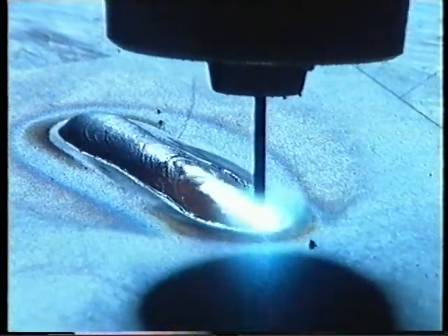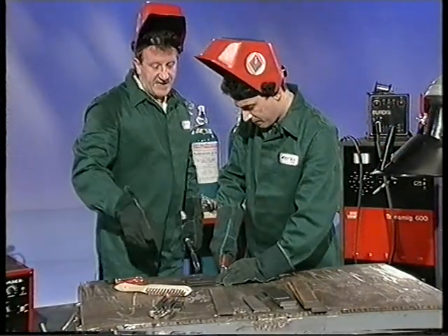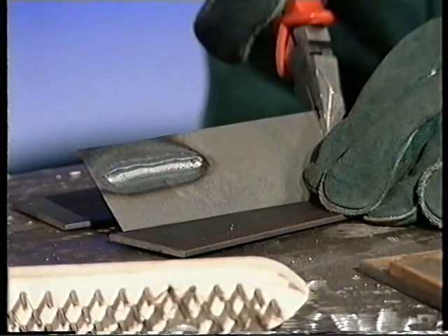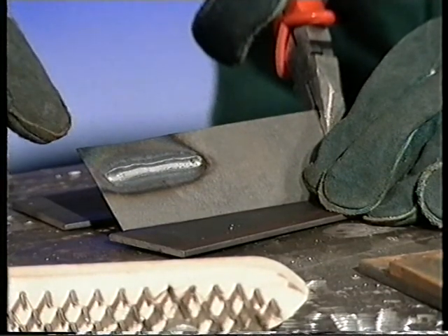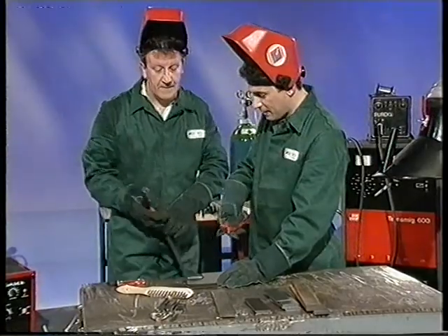That sounds spot on from here. And there, that's a nice balanced dip welding condition. You can see quite a flat weld bead, very little spatter. And on this material, this sort of thickness material, you really do have to move quite rapidly to prevent burn through. As you say, that is a problem with thinner material.